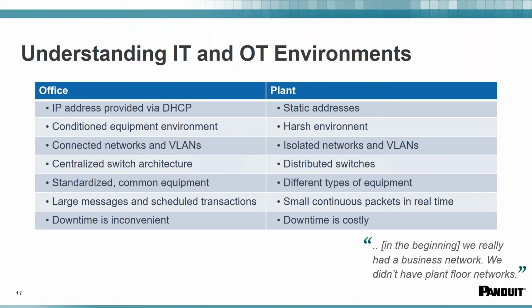So on the office side, we all know you come into your computer every day and you log into it, and you are given an IP address, which we call a dynamic IP address, that is assigned by a DHCP server. That is not the case on the plant floor. All the static IP addresses are pre-assigned. You already do that today.